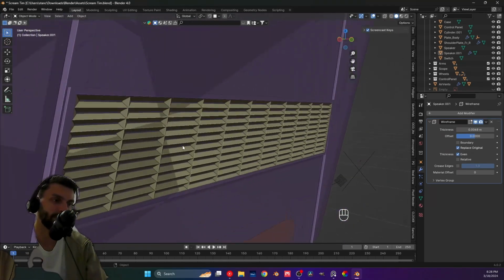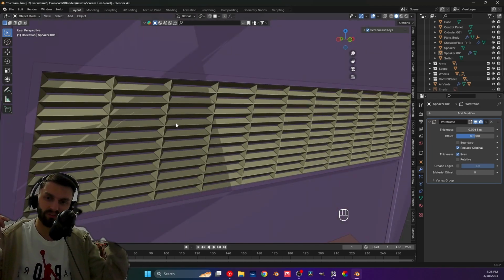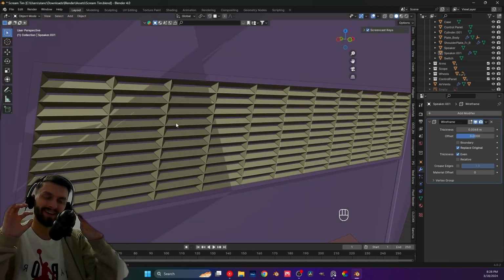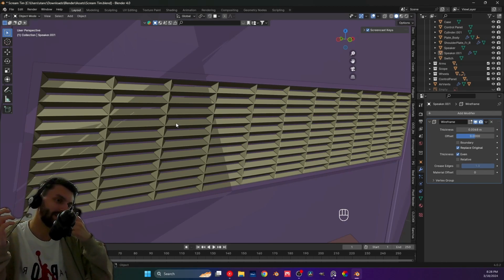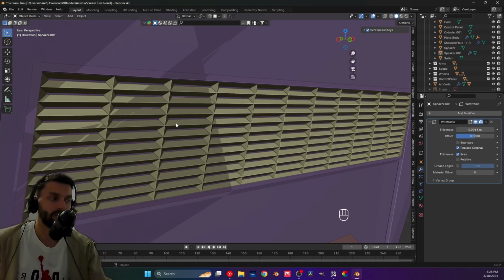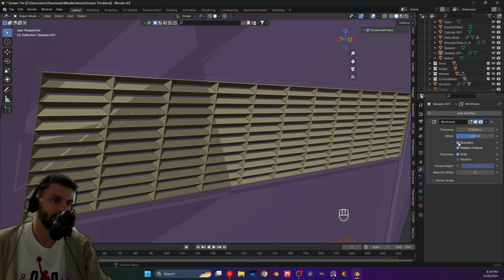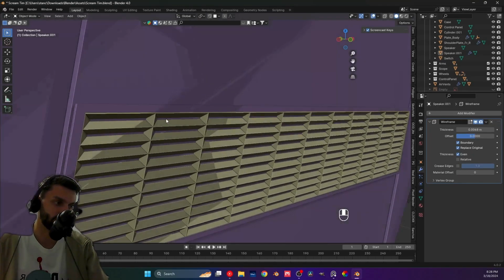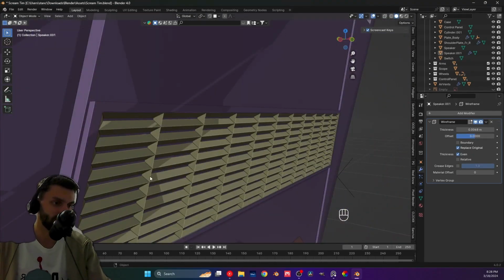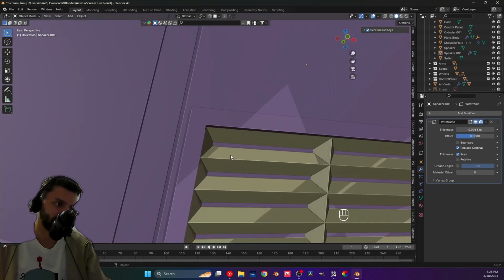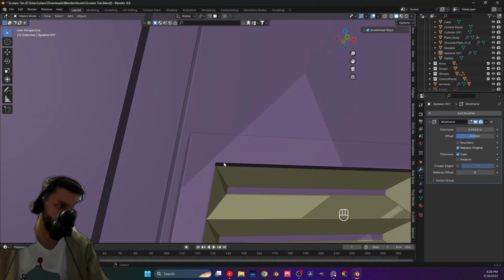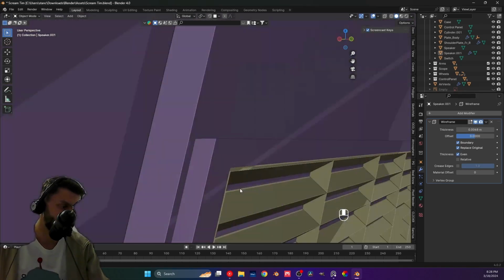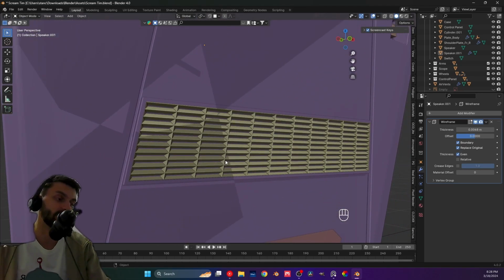And yeah, basically it takes the edges that you have from your mesh and creates, well, it wireframes it, right? So it creates the mesh around the edge, around the wireframe, which is where the name comes from. So that's why it works that way. And you can also use boundary to create it around your boundary, which does help, but again, it will add a little bit more geometry. But in this case it will actually help us a lot with this space right here. If you see it, that actually does make it a little more convenient for us.